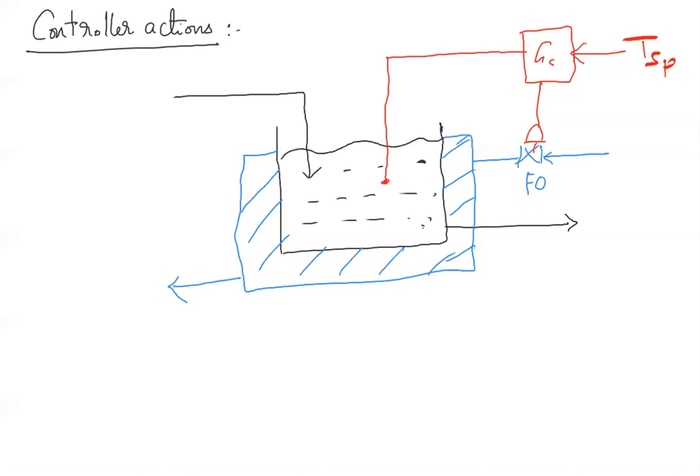Now the system is at steady state. This is 40 degrees. This is 1 mole per hour. This is, let's say, 60 degrees. Let's say 1 mole per hour. This is 1 ton per hour, 35 degrees. The valve opening is 30% because it uses 1 ton per hour. And this is 45 degrees centigrade. Clear?